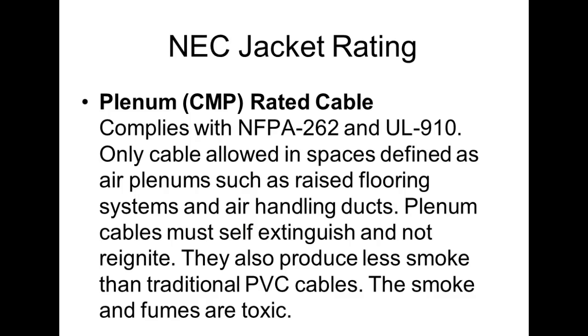A lot of cables don't like a lot of heat, and a lot of cables, when you catch them on fire, put out toxic fumes that will kill you dead. So a plenum rated cable should be non-toxic, and it also has a pretty good fire resistant rating on it too. There's almost nothing that's fireproof, right? You understand that? I mean, I can take steel, and if I put it in a hot enough fire, what's it going to do? It's going to melt.